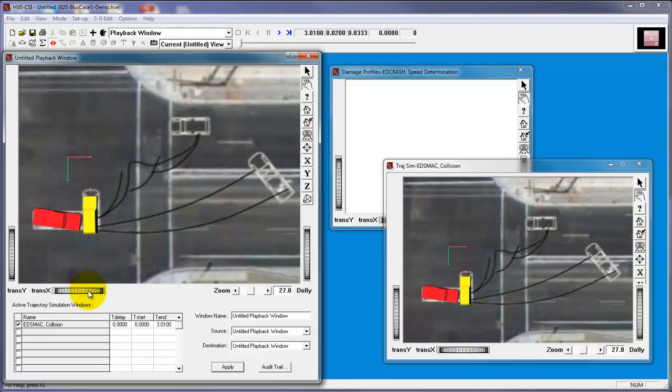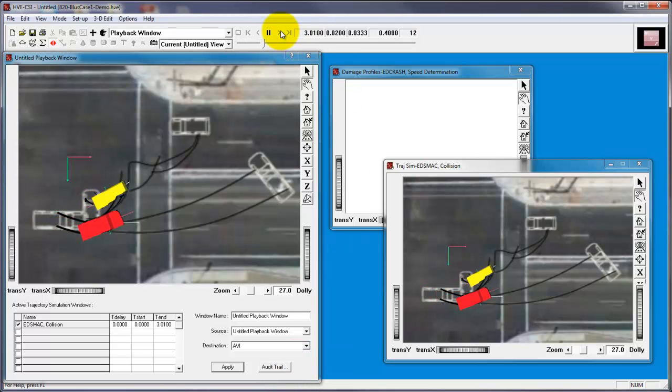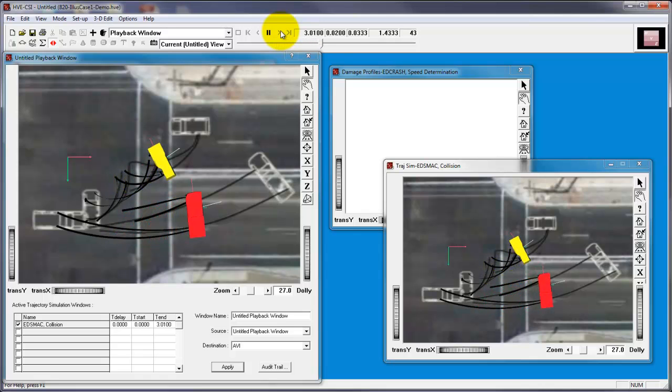Adjust the viewer settings to where you want the desired camera appearance, set the destination as AVI, adjust your render settings, and the movie will be recorded as it is played in the viewer. You can play this movie back within the same viewer, or you can view it separately in any AVI player or insert it back into your PowerPoint presentations.